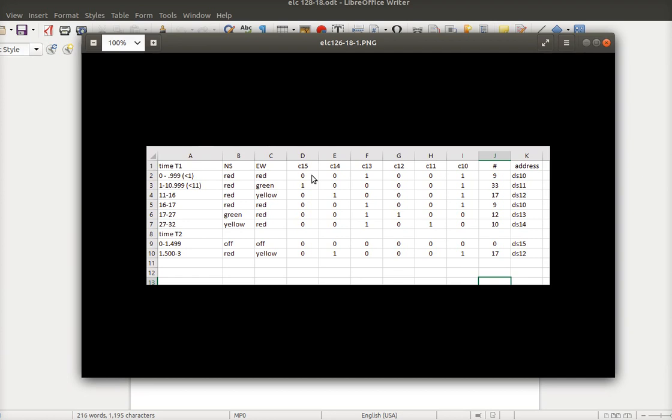So it's 16 bits and every bit's a 1. So basically, if your mask is set to Fs, you're not masking. If your mask is set to 0, you're masking everything. And so there's some number between all and nothing, and you can individually pick which bits you ignore.